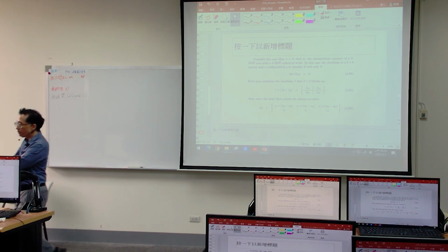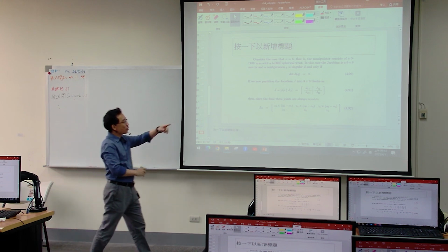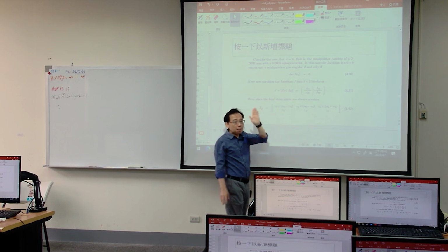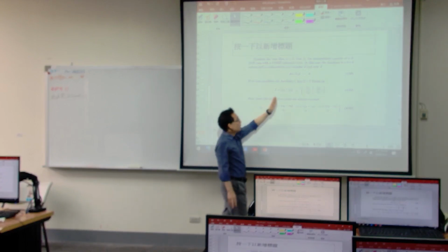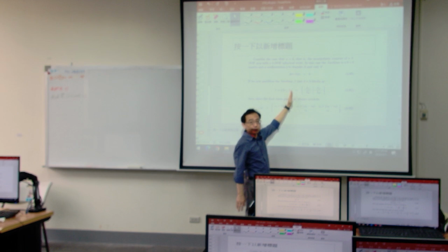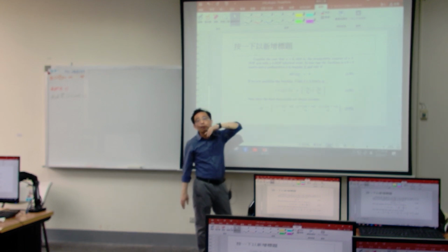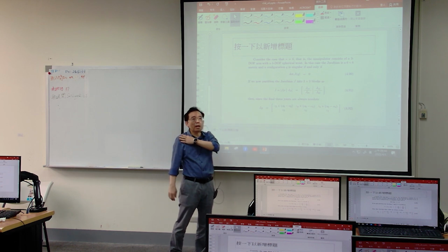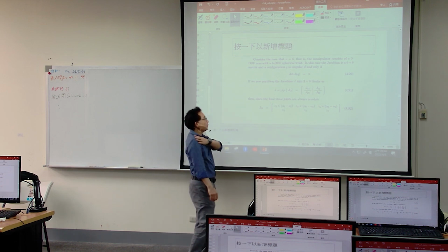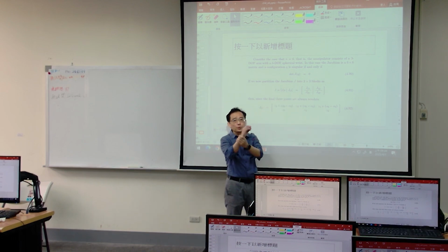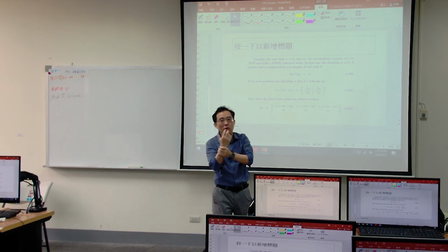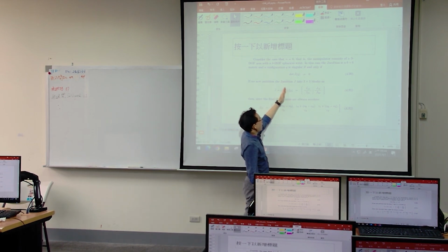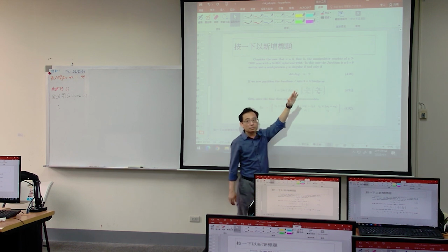We divide it into two sections. J is our whole Jacobian, and we divide it through the middle into section 1 and section 2. Section 1 is the arm section, which contains 3 degrees of freedom. Section 2 is the wrist section, which also contains 3 degrees of freedom. So they divide the arm section and the wrist section this way.